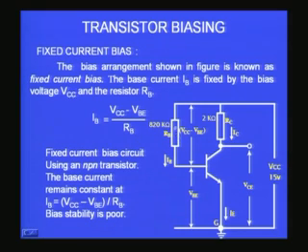Okay. Now, what about the VCE? Can I get the value of the VCE? Yes, you can also get the value of VCE and IC from this circuit. This is from the load line. We have already discussed that with 15 volts, you have 2 kilo ohms, there is a voltage drop across the 2 kilo ohms, and the balance is available at VCE. So, if you measure VCE, you can calculate IC.